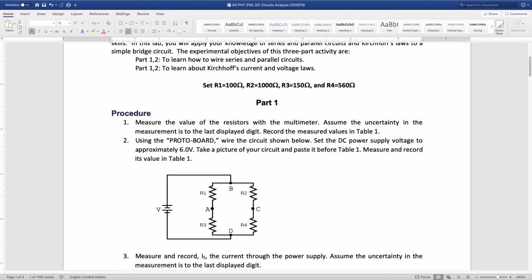But I bet you if you change the resistance value, the meter reading, on the 20 milliamp scale, you probably get 20 milliamps because the resistance of the meter is significantly more on a 20 milliamp scale. Though I wouldn't try it because you're at the limit of the scale. Yeah, and that's because of the meter in the circuit.